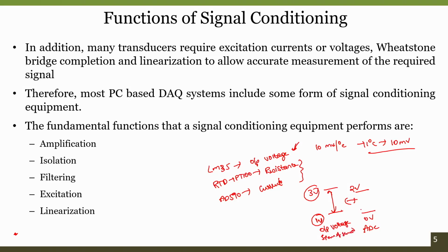So when we directly interface, even though the change between the maximum and the minimum is 2 volts, and the ADC is also capable of measuring 2 volts, because of this 1 volt offset, the ADC cannot measure the complete output range that the sensor is providing. As a result, because of these mismatches, you will be losing data, or the accuracy and the range of the system in this case is completely compromised.